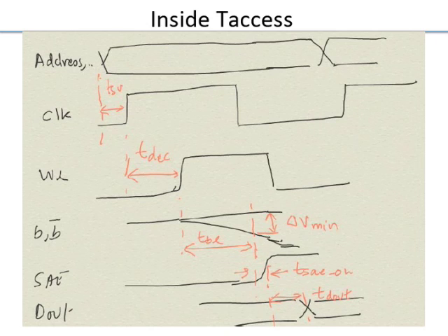When you turn on the word line, the zero side of the memory cell starts pulling down that bit line. So it's pretty much like a current source because all the transistors are in saturation, at least the transistor which determines the current is in saturation. So bit line time is essentially the capacitance C delta V by I. That is bit line time.